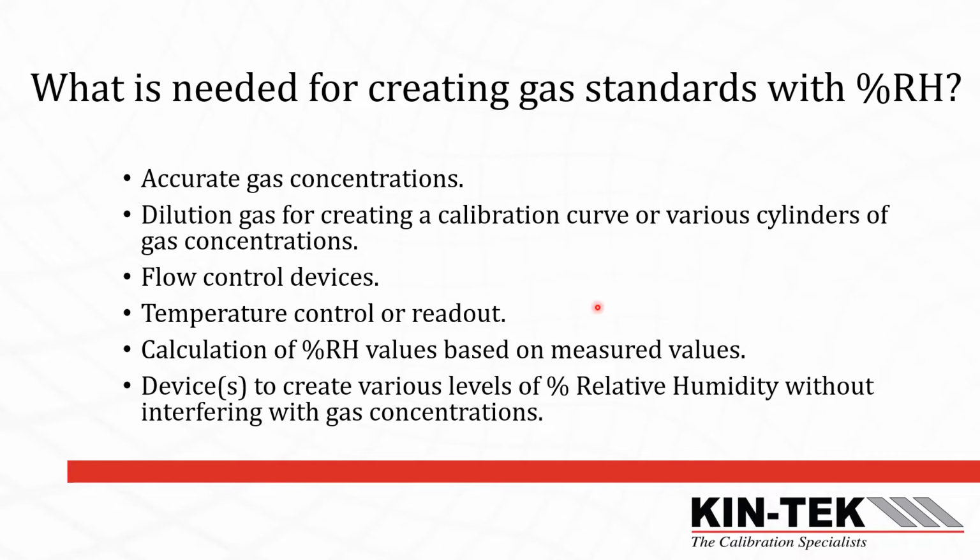So all that's fine, but what really is needed for creating gas standards with percent relative humidity? First, obviously you want the gas standard. So you want a dry gas standard that you're going to humidify. You need that gas standard to be accurate, so accurate gas concentrations. In addition, dilution gas is needed for doing a calibration curve, whether you're using various cylinders of a certain gas that you want to dilute, or you're using various cylinders of different gas concentrations.